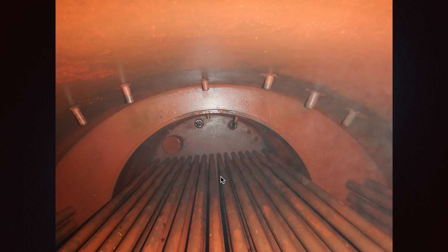for example for the purifiers, we heat our fuel to 98 degrees Celsius, the steam gives its heat, so it will enter at 120, 130, later on give all the heat, and our controller will be set up properly, so the amount of steam that we supply will keep it at 98 at the outlet. So the steam will condensate, it will go to 98 and start to go down, and the steam condensate returns back to the feed water tank.